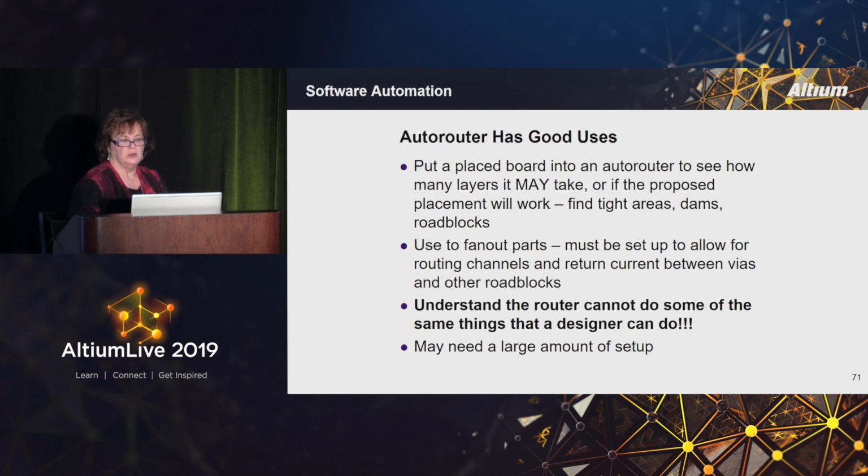Quick note here about auto routers. As I mentioned, I'm not an auto router person, but they do have good possibilities. You can place a board in an auto router to see how many layers it might take. It will probably tell you that it needs more layers than it does because it likes to change layers a lot. But it will give you an idea if you're close as far as the number of layers are concerned.